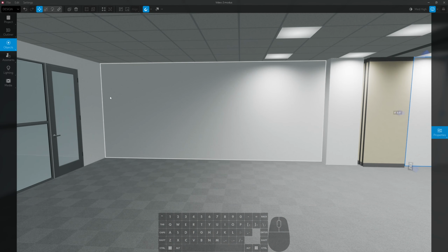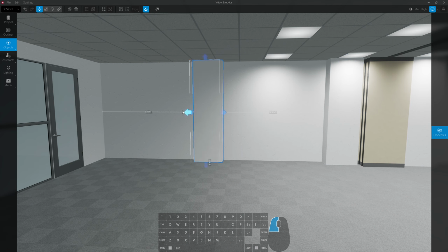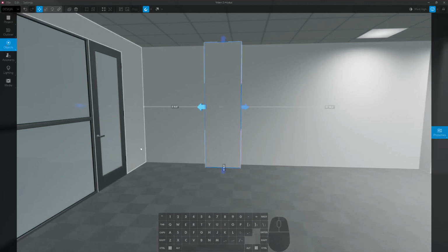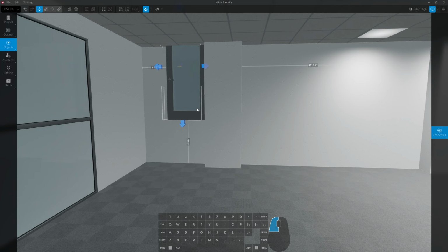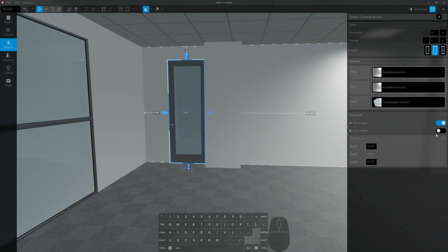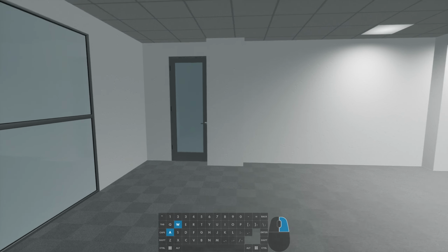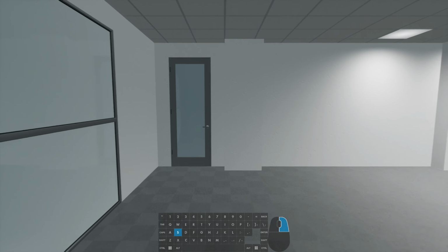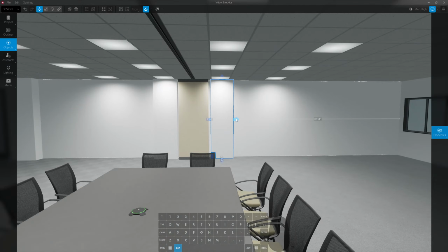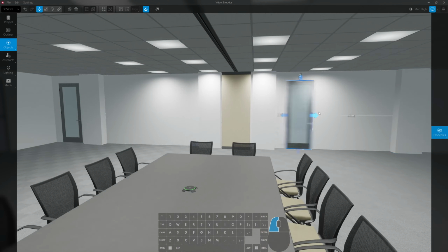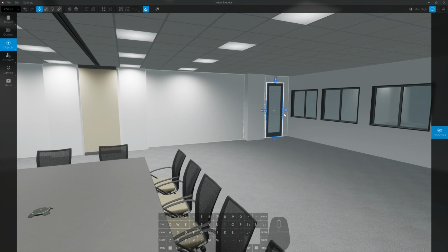I think I'm going to do something similar over here. I'm going to leave 5 feet for our doorway and for that swing open. So if I do this and change which way that door opens, and there we go. Center it in there. And I'll do something similar on this side. I'm going to alt copy, leave 5 feet, alt copy, and center it in there.